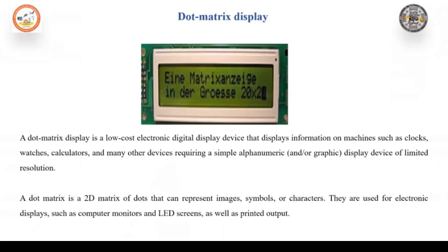In this scheme, the LEDs are not lit continuously, but are sequentially lit by scanning in a vertical strobe or horizontal strobe mode. In the vertical strobe mode, information is addressed to the display by selecting a single row at a time, energizing the appropriate LEDs in that row, and then proceeding to the next row. In the horizontal strobe mode, a single column is chosen at a time.